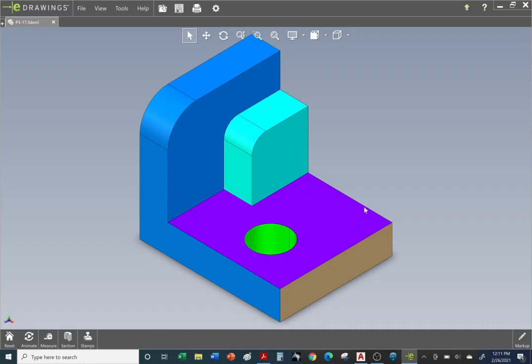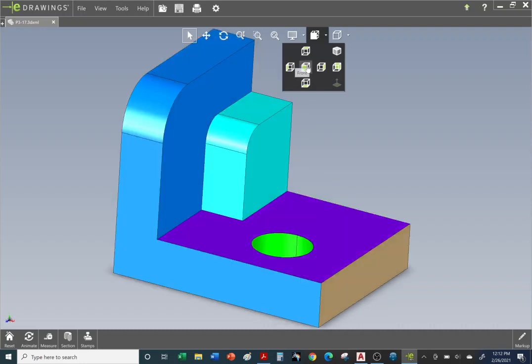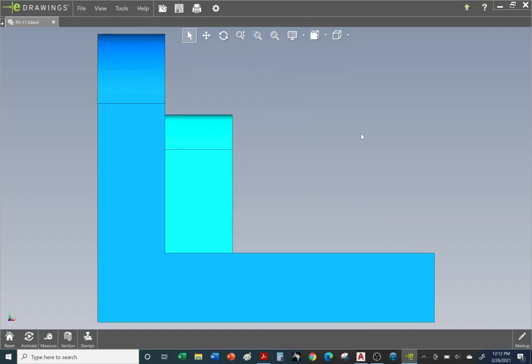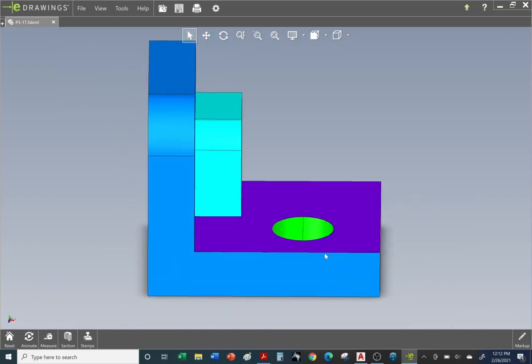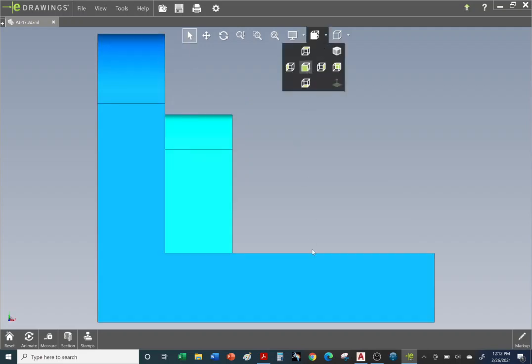All right, so let's go ahead and take a look at our front view. Okay, so here's our front view. Let's go ahead and draw these object lines, and keep in mind any hidden lines also. So we don't see the hole if we're standing in front of the building. So again, imagine we're in front of the building. Imagine this is a 4-story tall building. Let's go back to front view. So obviously we cannot see that green hole, that circular hole. So we'll take care of that with hidden lines and a center line.